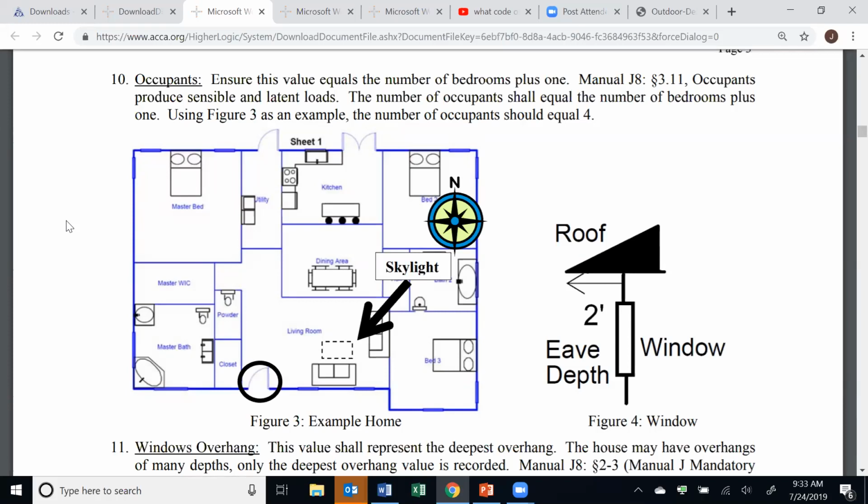These are some tough questions that the committee doing Manual J had to discuss, and we had to put down a stake somewhere. If you go to 9 out of 10 homes that have a family in them, you've got 2.4 kids and mom and dad. And so we went with number of bedrooms plus one.